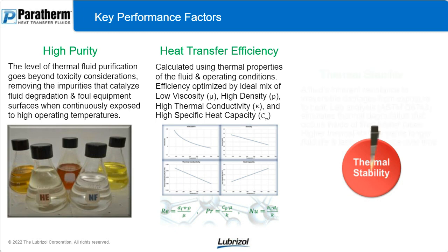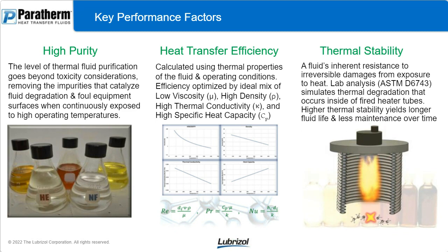Thermal stability, the fluid's inherent resistance to irreversible damage. Key point, irreversible damage. One of the red flags that we'll talk about moving forward is the ability to recondition a fluid or not. A lot of the damage that happens due to thermal stress cannot be fixed by putting an additive pack in or putting some kind of reconditioned magic dust into the product, right? These products are going through a thermal stress that's typically going to be irreversible. So once the problems happen, the fluid usually needs to be changed out, and cleaning and all kinds of things need to happen.